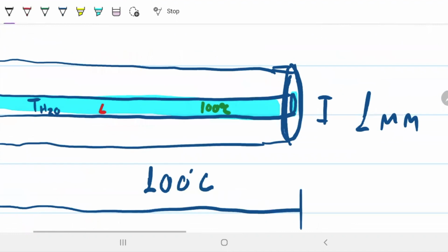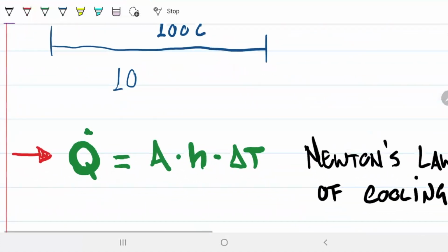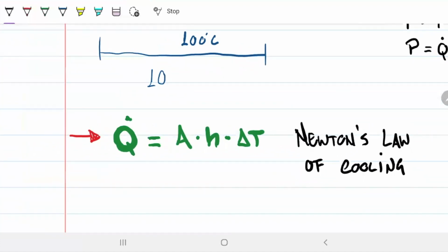The idea is, let's zoom in on this beautiful drawing of mine. We have water at 100, it's boiling, and this water is responsible for taking away the energy being created because of the electrical current flowing through the tube, right? Because there's a difference in temperature, delta T drives heat transfer, and therefore we will find a heat transfer Q from the 125 to the 100. If we're only considering convection, then we only need to worry about Newton's law of cooling, which tells us that